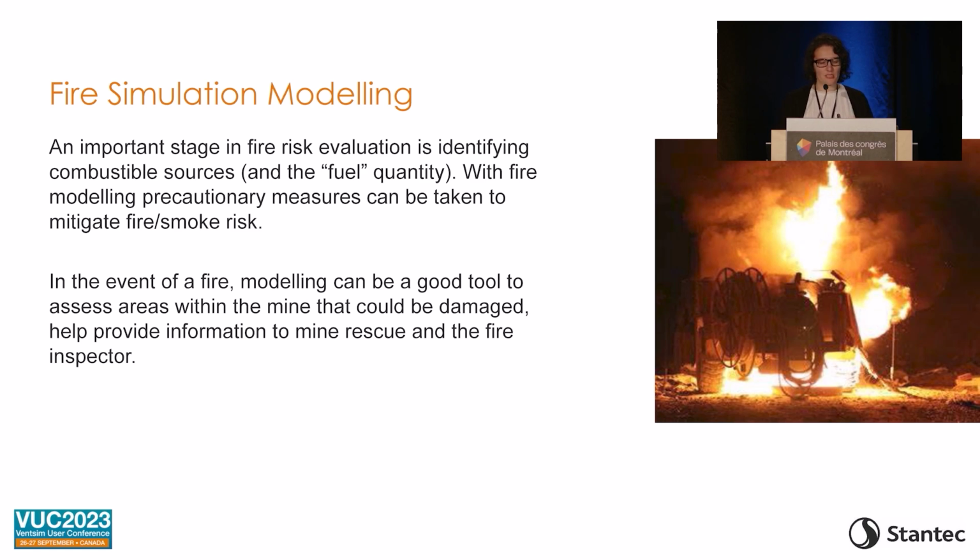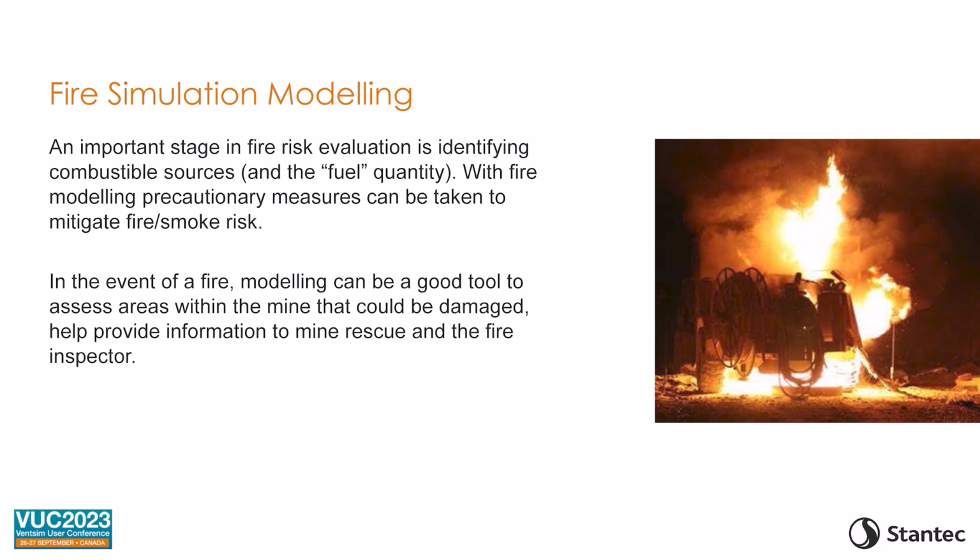When you do the risk assessment, you should preemptively be able to do fire simulation in areas where, for example, a workshop is an area where there's a lot of combustible sources. So that's a good area to already have a plan in the mine. So if something happens, you know how to address it. But sometimes, you've got a truck that catches fire in a location of the mine, and you can't model every single instance of when this happens. But at least if you've got the presets already set up in Ventsim, if that happens, you can model it.